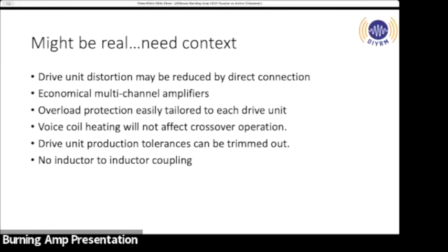I had a two-way speaker that I was working on for somebody on the bench. The crossover was already separate. What I did is I disconnected the tweeter crossover and I shorted out the input to the tweeter crossover. Not the tweeter itself, but the tweeter crossover. So now that is giving me the impedance that you see with an amplifier, because that amplifier is going to be a short circuit, right?